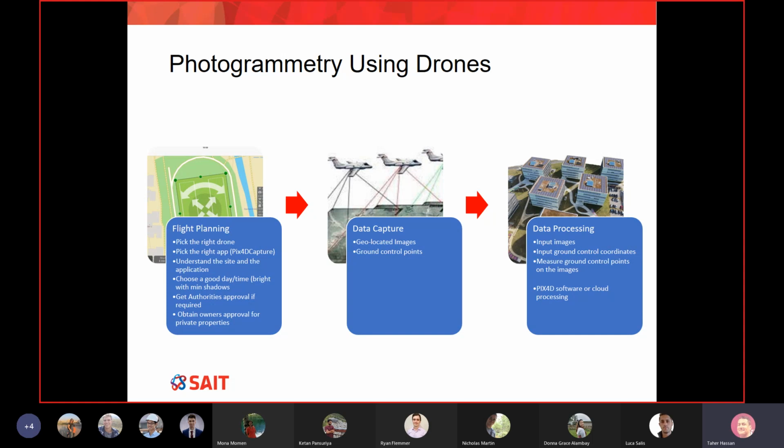I need some drone. Should I buy or use the DJI Phantom 4, or should I buy Bix4D? It depends on the nature of the project and the size of your project. If you have a linear project, I'm referring to things like electrical cables, like a power cable, or roads. Those are linear projects. They extend for many kilometers, and the width of your project is kind of tiny, maybe 40, 50, 100 meters wide.